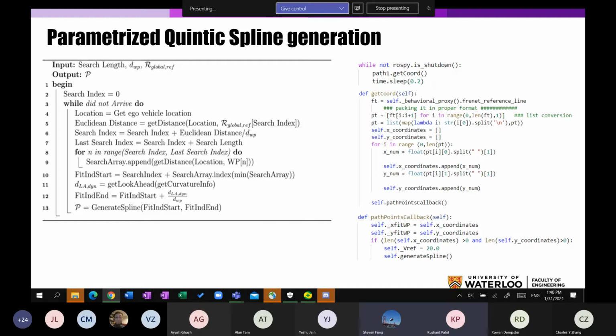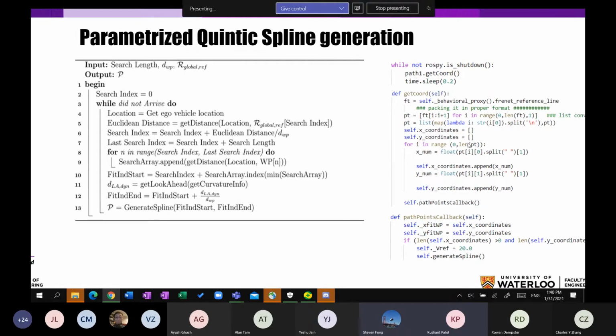As we find the parameters, we have certain constraints, such as maximum curvature. The maximum curvature should allow us to plan lane changes smoothly, even in the case of crisp waypoints. Then we use the Carla route planner to find a route from an initial point to a random target point. So this was the scenario of the Carla route planner, but now as we are trying to integrate it with the autonomous stack, the locations will be passed on from the behavioral planner.